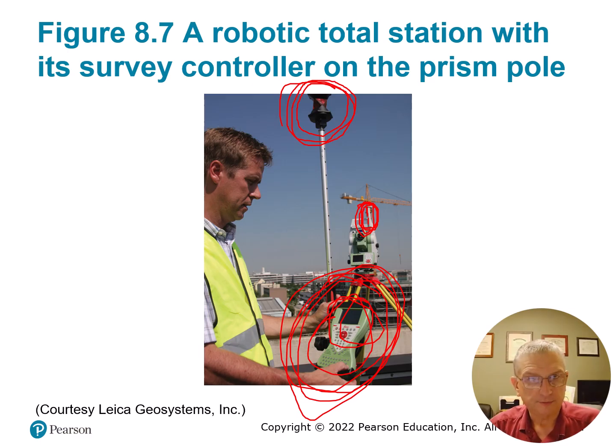And you tell it through functions on the data collector: find me, turn to the left, this is point number 127, you key in your description. If it's a single foresight and go, you tell it that. If you need to plumb it up, probably use your bipod and turn a set of angles. You can do that as well.